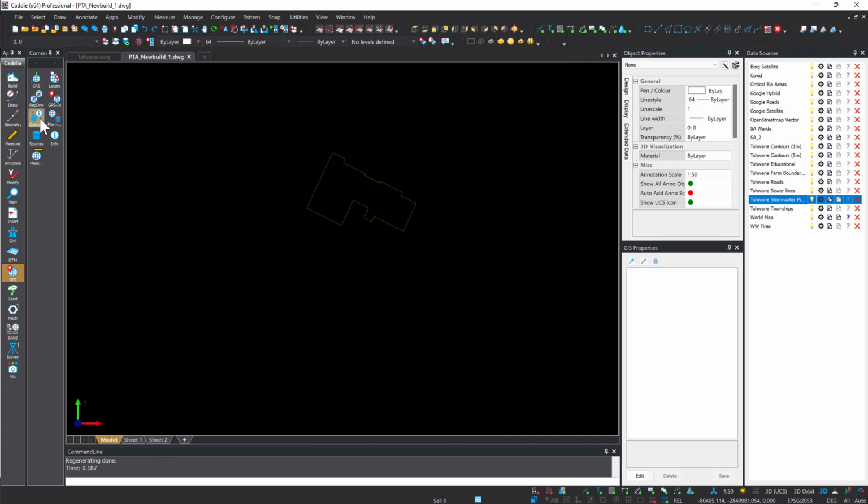And now if we can go and check that, so we can just say query points. And what's the top corner? We'll go into this auto snap mode, sit there, and 25.77542, 28, that's correct. At this point now, this is a completely accurate lat and longitude, so it'll tell you the lat and long of any points on the building. So that's got this building georeferenced in a sensible coordinate reference system.